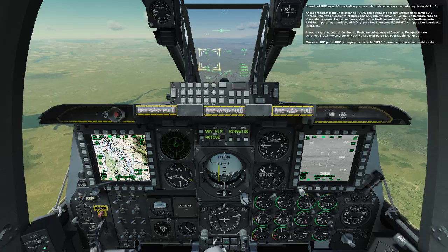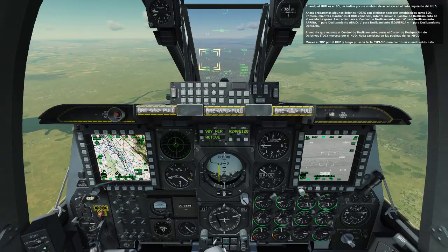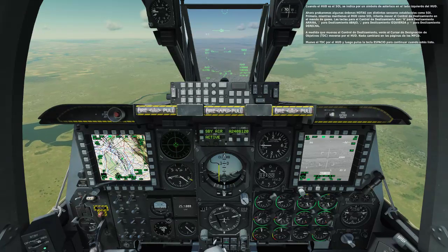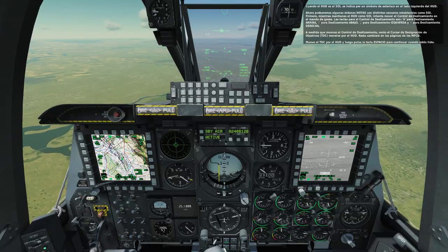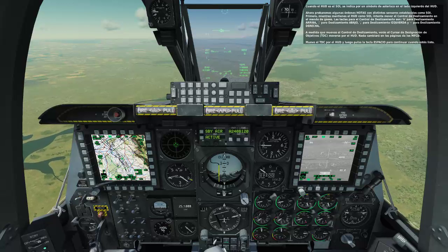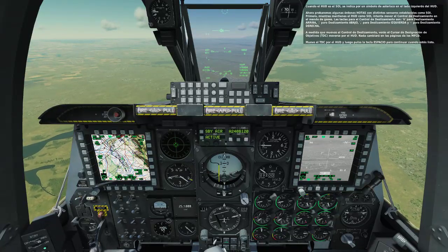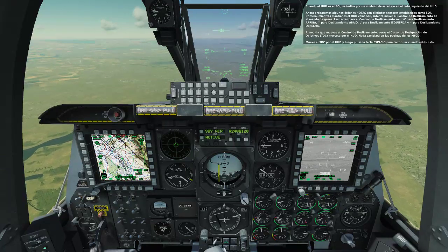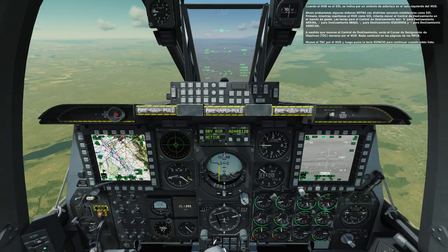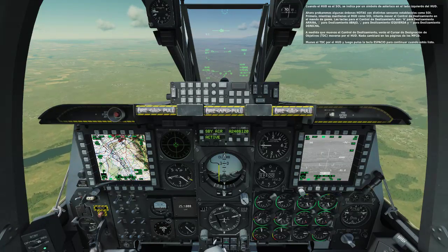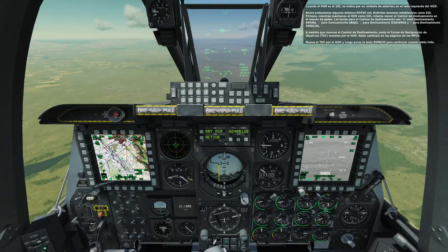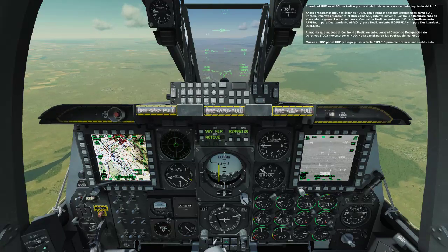Okay. When the HUD is SOI, it is indicated by an asterisk on the left side of the HUD. We'll now try some HOTAS commands with different sensors set as SOI. First, while keeping the HUD set as SOI, try moving the slew control on the throttle. Keyboard commands for slew control are semicolon for slew up, period for slew down, comma for slew left, and / for slew right. As you move the slew control around, you will see the target designator, TDC, move on the HUD. Nothing will change on the MFCD pages.